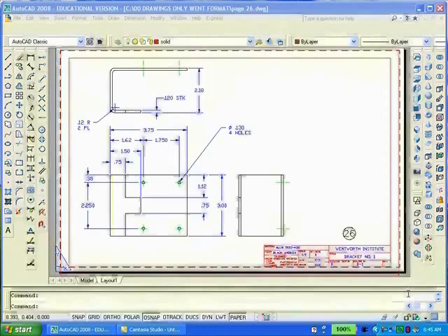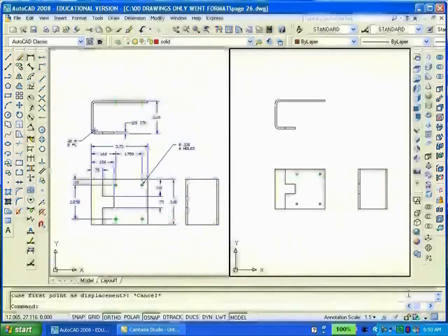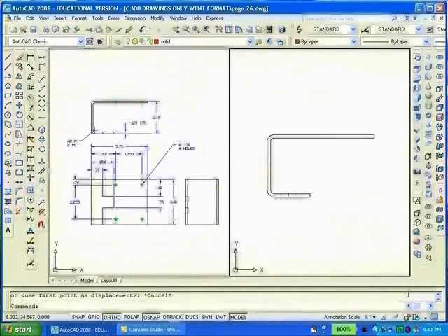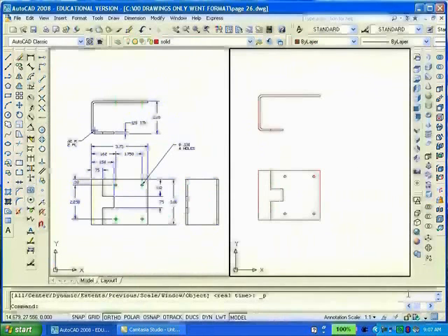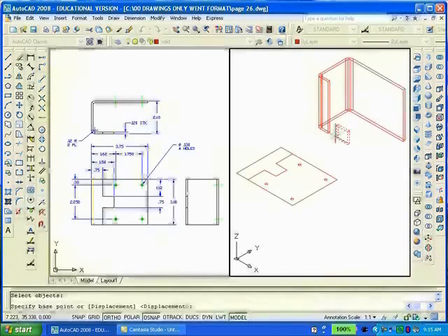This is an abstract of tutorial 26. In this drawing, I used a polyline to trace over the top view, subdividing it into two parts. Then I will move those profiles to the upper right, and of course make certain that both are closed polylines. I move into the southeast isometric view and extruded the large profile to a height of 3 units and the smaller to a height of 7.75 units. And with the O-snap set to midpoint, move the parts together and union them.